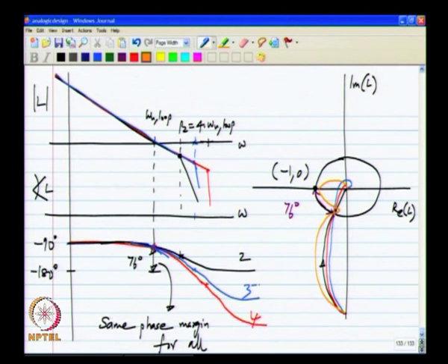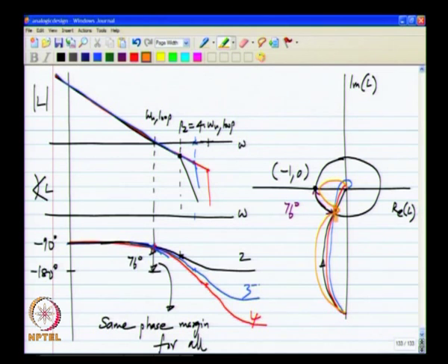But we are looking at relatively simpler systems where you have either extra poles or some extra poles and extra zeros. In that case, it is safe to say that if the phase margin is 76 degrees, inside the unit circle it kind of goes straight towards the origin and does not come closer to -1. So, the magnitude more or less goes down monotonically. The real problem will be if the magnitude after falling below unity stays close to unity and the phase angle increases, then it will come closer to -1,0.